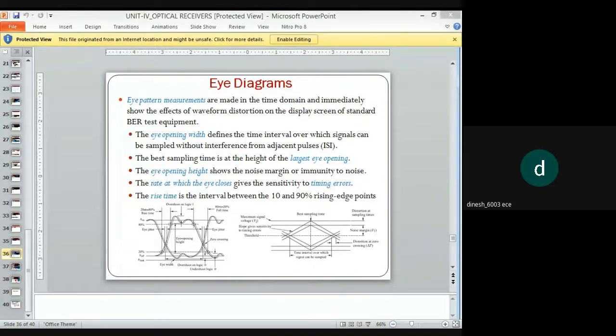You can see that ONT packet 1, ONT packet 2, ONT packet 3 have a guard time of T, where up to 20 decibels can be present. So this is your guard time. The relative received power level will vary depending upon the ONTs. This is from the closest ONT, this is for the farthest ONT, and this is an intermediate distance ONT.